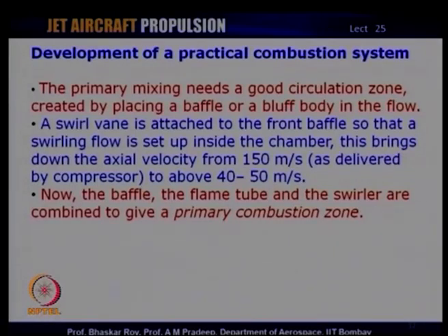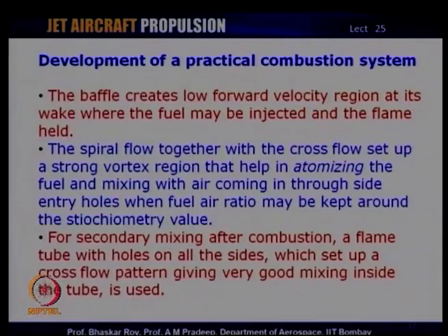The development of a practical combustion system also ensures that the baffle that you have creates a low forward velocity. The spiral flow that it creates helps what we had called in the last class the process of atomization.